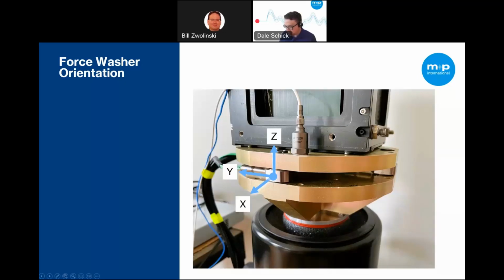For what Bill was describing earlier with the engineered bolt and the ring nut, this would have made for a much easier installation. Because if you can imagine that I have these force sensors on the ring and they have to be expertly positioned, then you have to put the force ring on top and then load the bolts in the top. It's very difficult to do that, especially just with one person.